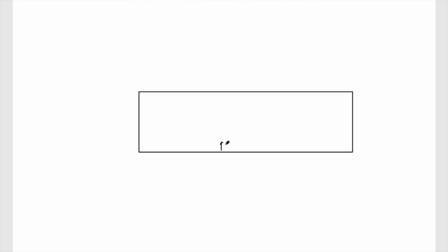This is again my p-type semiconductor, which is sometimes also called a substrate, because this is the base where I will be fabricating my transistor, the MOSFET. We will start the basic structure of the MOS, where I will be digging two kinds of wells, or islands, of N plus material. These are N-type semiconductor.